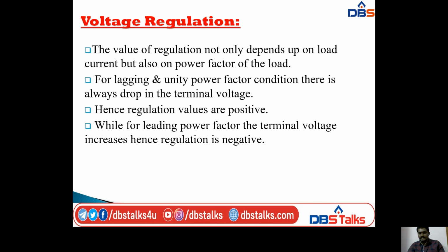While for leading power factor, the terminal voltage increases. Hence, regulation is negative. So clearly, it shows that for lagging and unity power factor, the regulation values are positive, and for a leading power factor, the regulation value is negative. Okay. Next,